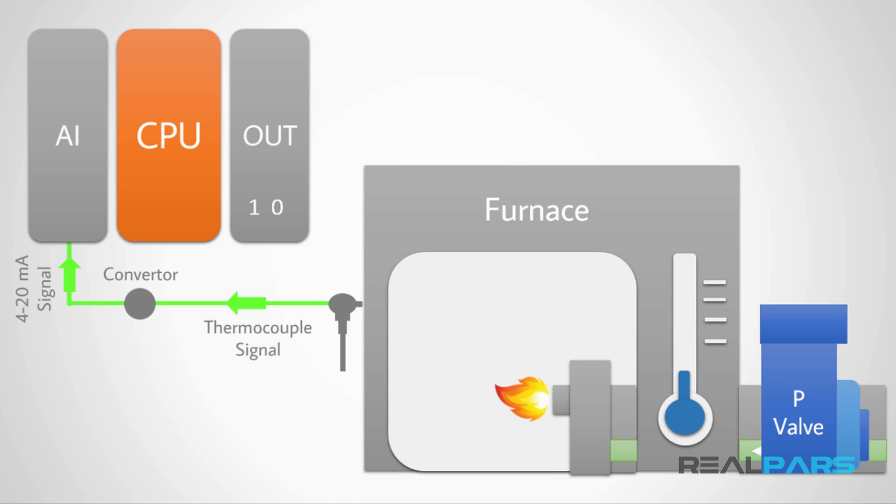Proportional valves usually receive a 4 to 20 milliamp signal at the input. The amount by which the valve opens up in these kinds of valves is directly proportional to the electric current that they receive. The more the applied electric current, the more the valve opens up.